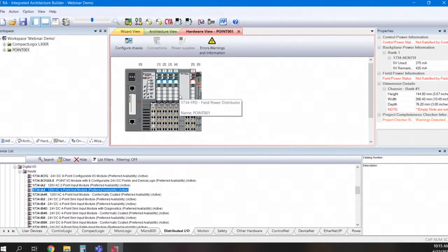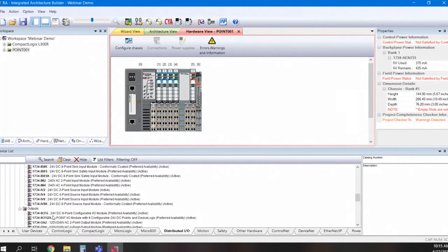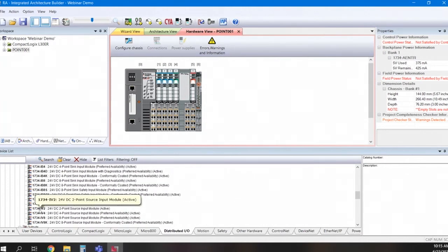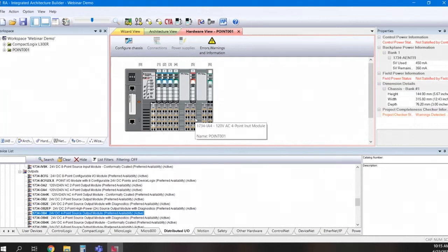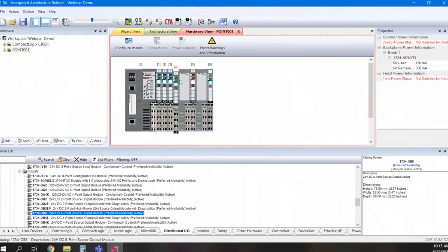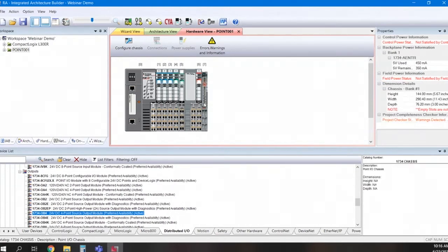It added it automatically. So it'll go right through, and if for some crazy reason I wanted to do a configuration of one AC module and then do a DC output module right after, which I would not recommend, it'll throw in another one to switch that bus back to DC. So it knows exactly how you're configuring it, so you don't have to worry about what you need in between. If I want to rearrange these modules, let's say I want to insert a slot after this OB8, I'm going to take this, drag it over to there. It'll just remove those field bus modules and get you all configured, ready to go.